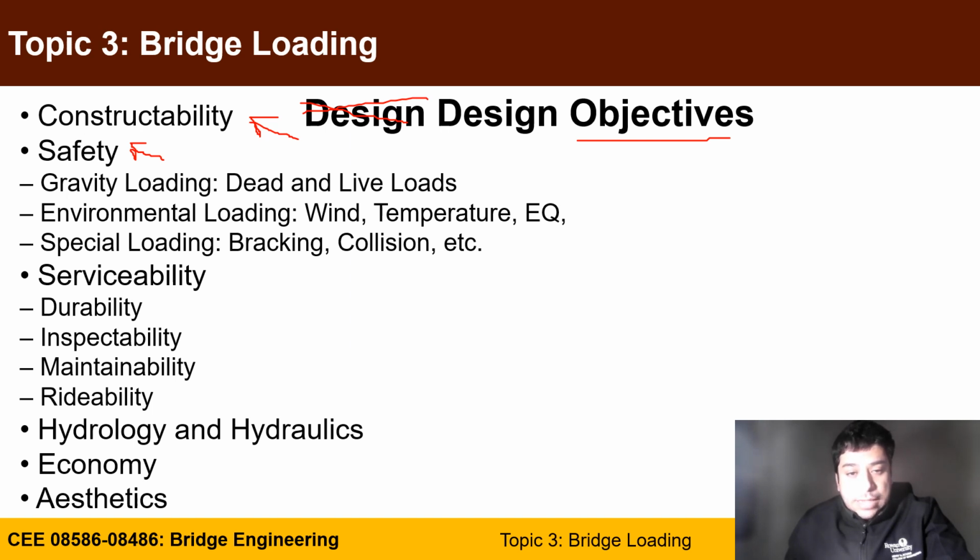Also, we need to ensure safety by carrying the loads from the bridge down to the foundation, so safely carry gravity loading such as dead load and live loads. Also, ensuring environmental loading such as wind, temperature, and earthquake will not damage our bridges beyond certain acceptable limits. And also special loading like truck braking force or collision, etc. So this is related to safety of the bridge and the traveling public too.